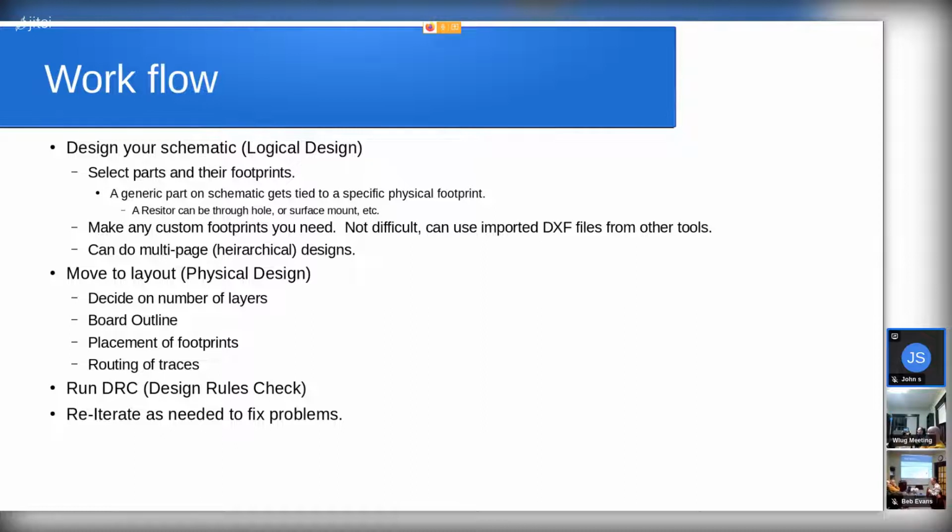When you're doing a 4-layer board, usually one layer will be a ground plane, one layer will be a power plane, and the other 2 layers will be your signals. And you tend to do it so one layer runs north-south, and the other runs east-west for your traces. This way you can get around sort of like a grid of streets. Think of a trace as flatland: it's 2-dimensional. You can't run a trace over itself unless you drop down to another layer.